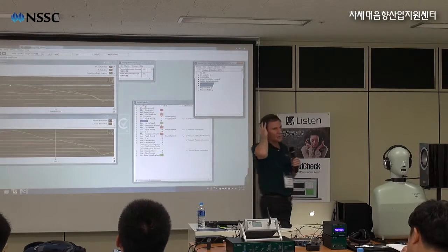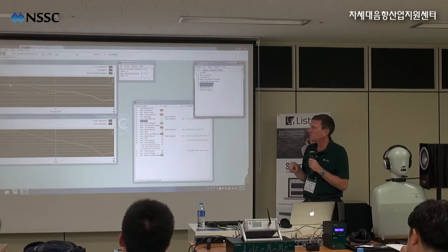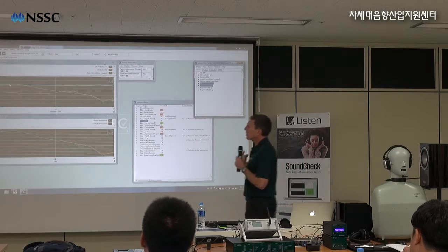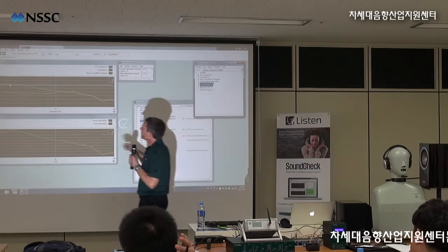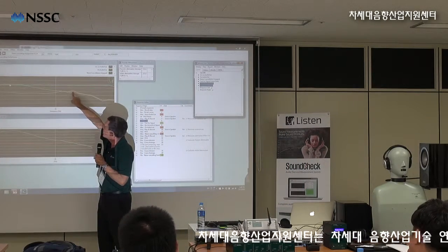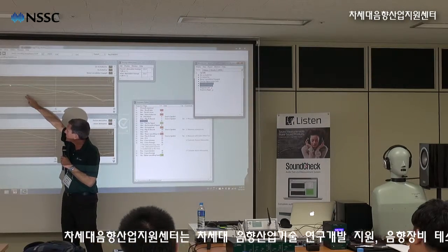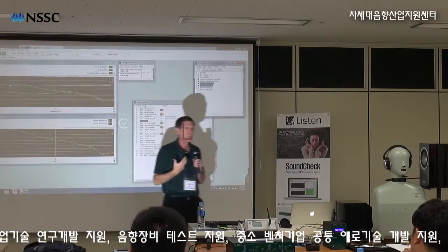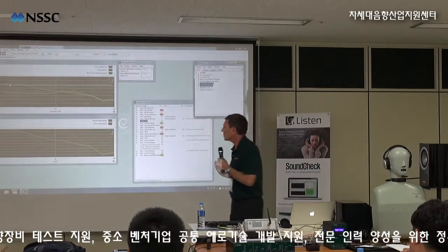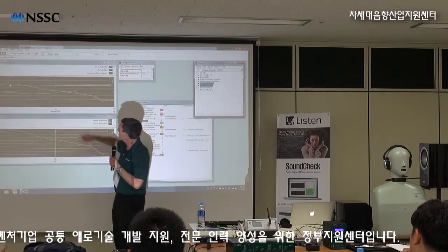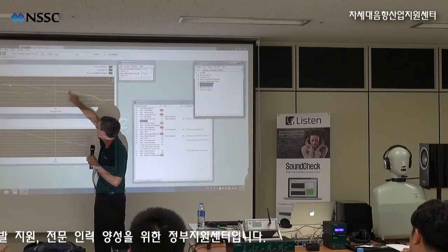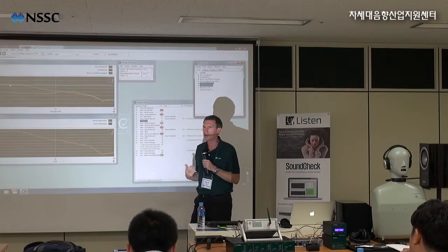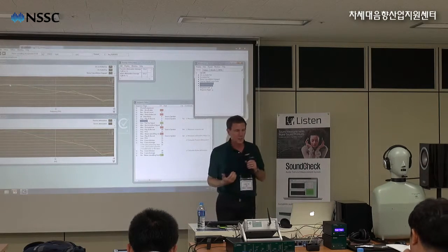Because we still have the passive attenuation, but now we have the noise canceling circuit turned on. And again, something interesting happens. We get a little bump here. So at low frequencies, this is great. We're getting on the order of 20 dB of attenuation. But if you look carefully, the active noise canceling circuit is, instead of attenuating, actually amplifying, which is not what you want.